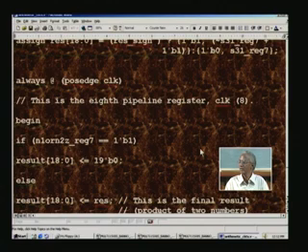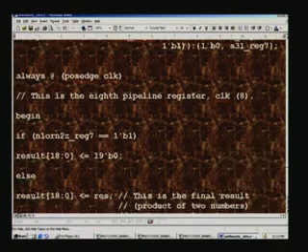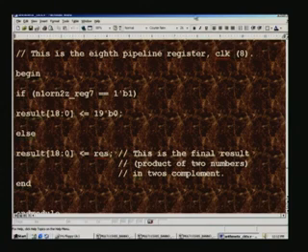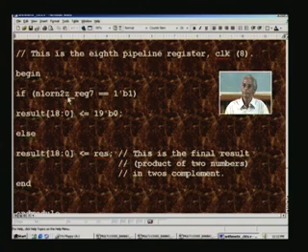What we have to do is merely assign this final value which we had just now evaluated, depending upon the sign bit. What we did not take care of is whether n1 or n2 is 0. Earlier we had a 0 flag propagating all through, implying whether the final result is 0 or not. The final result is 0 if n1 or n2 is 0.